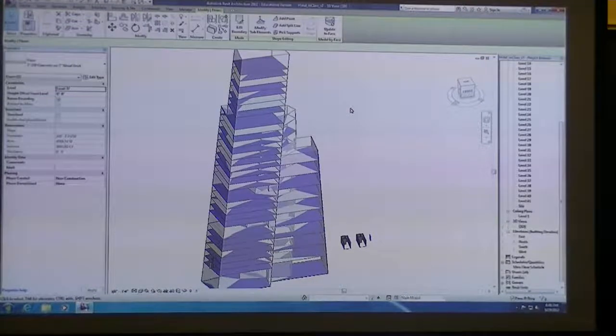Basically, what we want to do is first find out how much area we have on each floor and come up with a method to calculate how many people could be on a floor at one time, assuming this is just a hotel. By code a hotel floor is considered an R2 occupancy, residence, and you would calculate your floor area per person at 200 gross, meaning 200 square feet per person. Because we're also going to have lobby spaces, and if you had conference or meeting rooms on a floor, those would be assembly occupancies and you'd have a lot greater number of people on that floor.